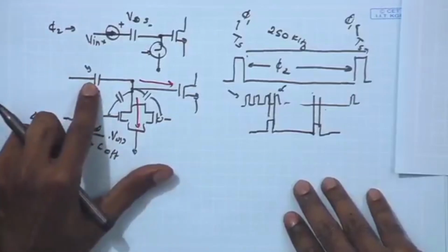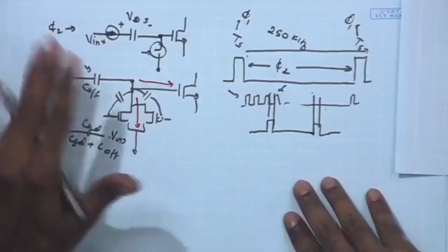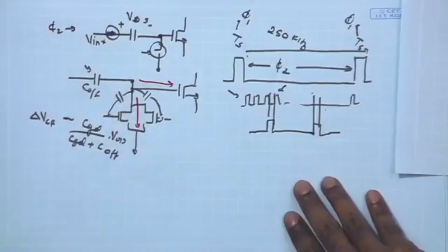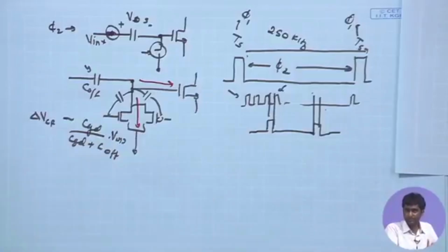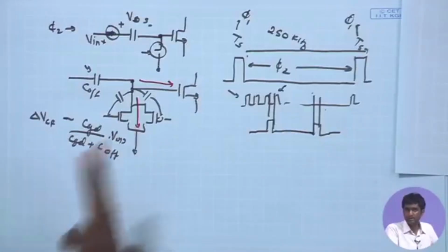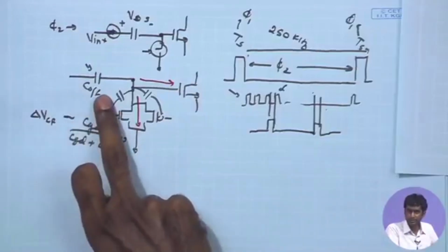So, 1 picofarad, as I say, is not a very serious limit, because we have seen the major capacitance is coming from the ramping circuitry. For that circuitry, for robustness purposes, we have kept the current magnitude at least around 100 nanoampere or 0.1 microampere, and that gave us the maximum amount of capacitance around 10-20 picofarad. So, as compared to that, the overhead here will be relatively small.